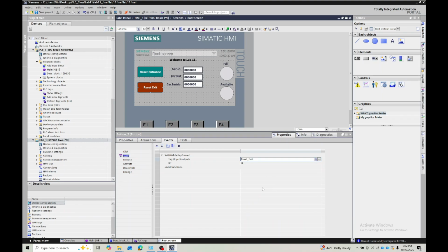As I mentioned, having the connection between the memory M0 and the HMI tags is fine, but for a word it is not fine. That's why we use that move function, we avoid that. But for just one bit, it's fine, so you see I make a connection between the HMI tags and the PLC just for 1-bit memory. So we should be good here.